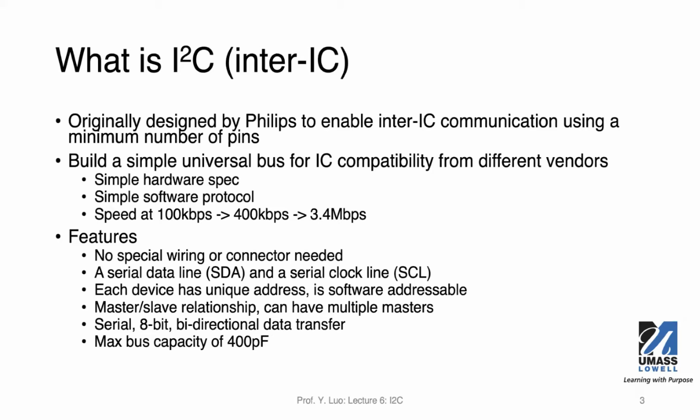The operation speed of the bus is 100 kilobits per second or 400 kilobits per second for most of the ICs. Newer ones can support 3.4 megabits per second. Now, this is not very high speed, but for most of the ICs that you will work with in the embedded system domain, these data rates are sufficient.